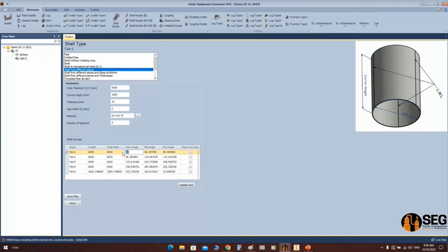Here, let's change the first longitudinal welding line orientation and click update. Automatically, the orientation of the other welding lines will be calculated. So with any change here, for example, if you make this 5 meters and 0.5 and click on update, you can figure that the last blade is automatically calculated. So let's go back like that.